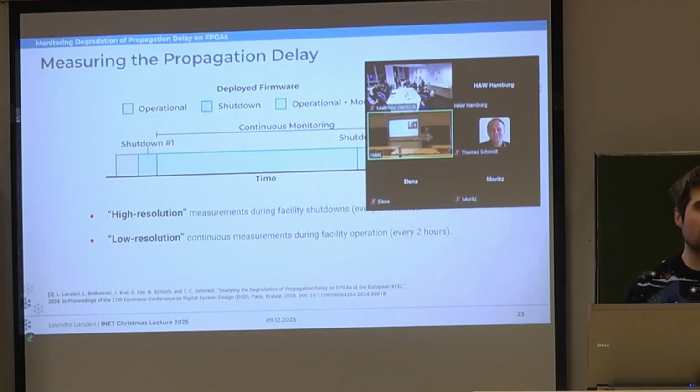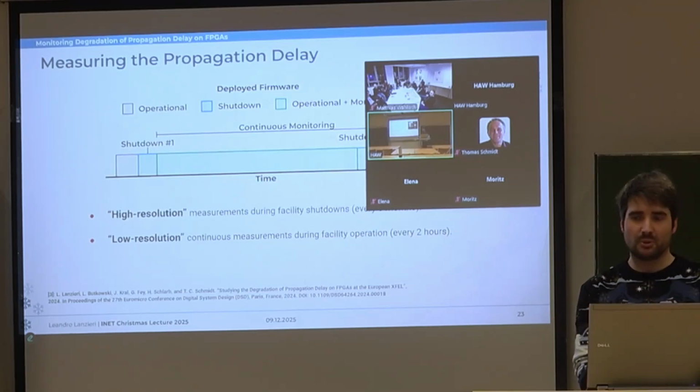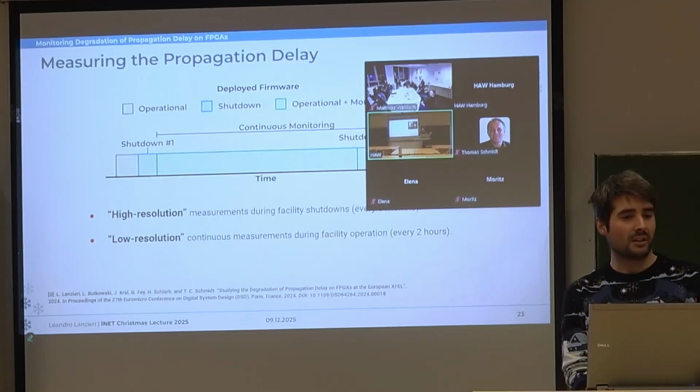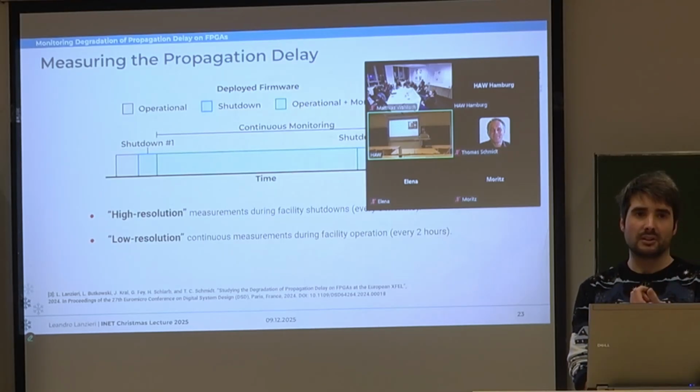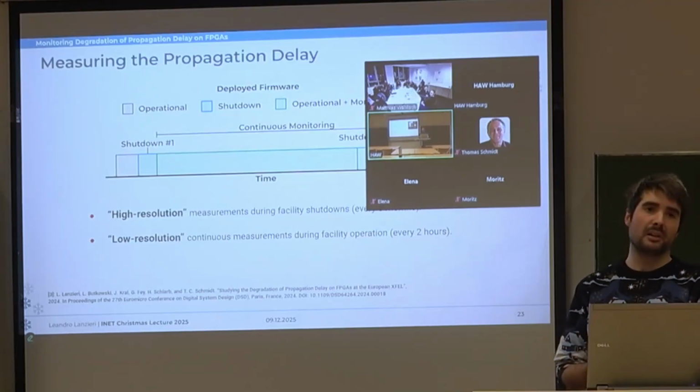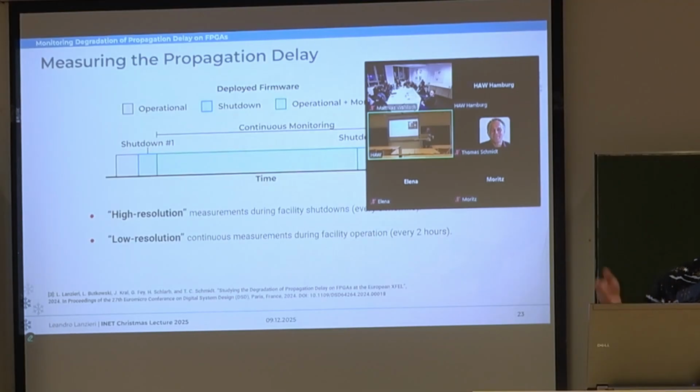Yes, it changes. In 3D FinFET structures, for instance, you have self-heating effects because of the 3D structure in the silicon. They are not that good at dissipating heat, which means effects like NBTI get much more extreme. Also, we are shrinking the footprint of each transistor but not shrinking the applied voltage at the same rate. The electric field is much bigger in comparison, which induces more diffusion. That is the main cause for NBTI.